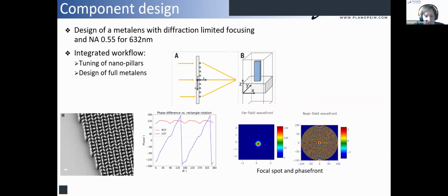So what you do as a designer is you identify through ray tracing or through theory what's the required lens profile, the wavefront that you want, and you map that back to the different structures that you have available that can be manufactured. Then you calculate what should the shape look like, what's the GDS, what's the projected phase function, and what's the final efficiency, point spread function, and so on and so forth. So all of that is then calculated.